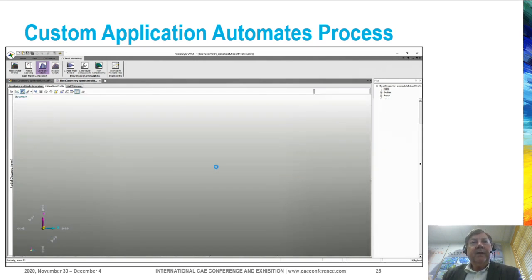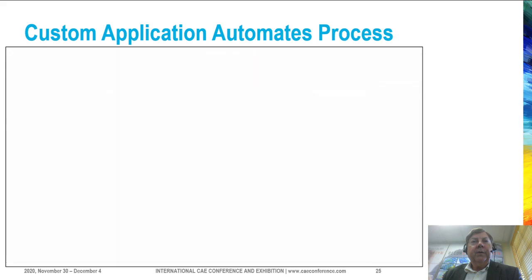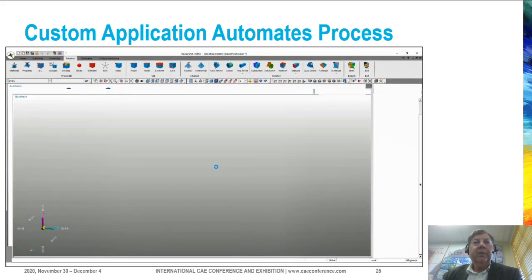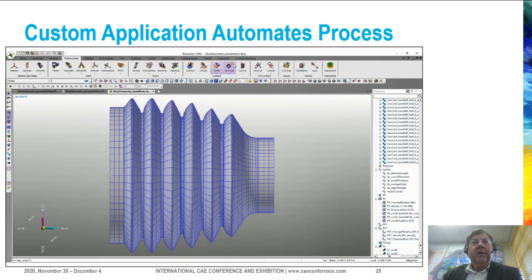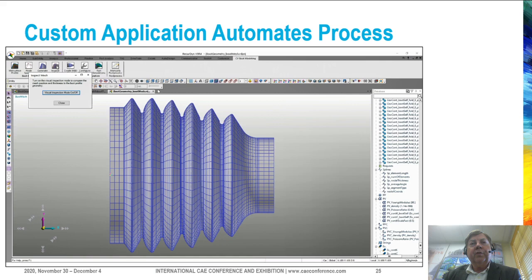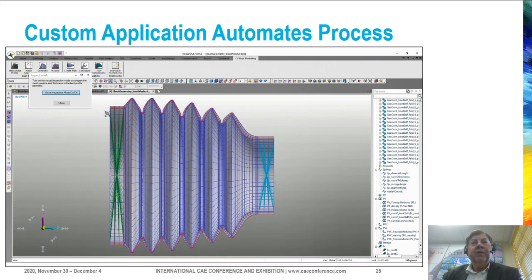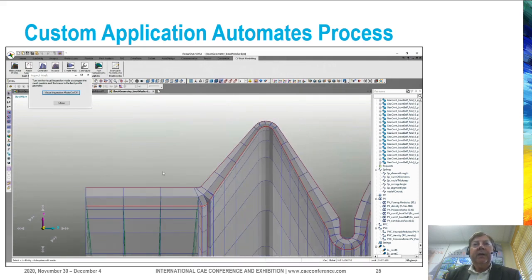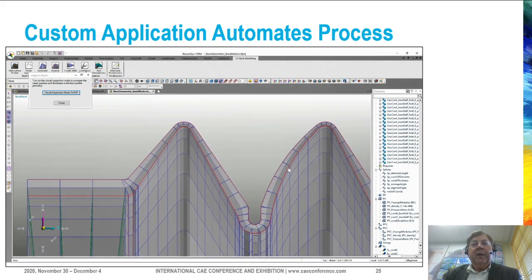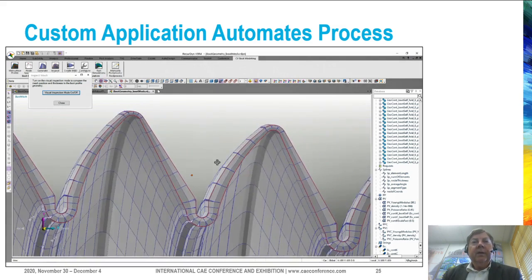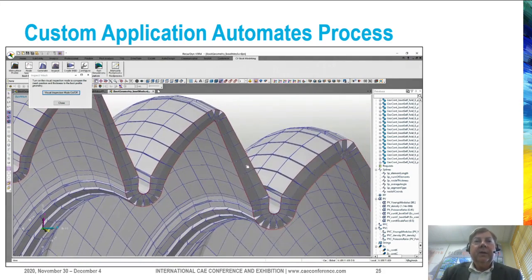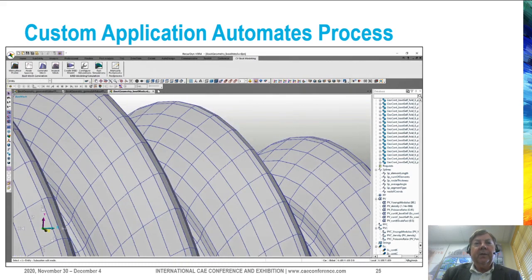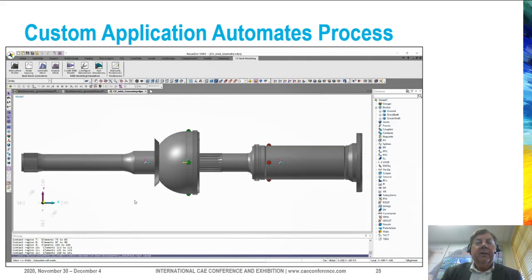And so then with that, we can go through the next stage of the process, which is to just go ahead and create a mesh. And you can see all the details in the mesh. The user can control the resolution of the elements at the outer tips as well as at the root of each fold, because that's the most sensitive thing to get accurate results. And here we're seeing the thickness of the element applied graphically. So that's a preview mode.